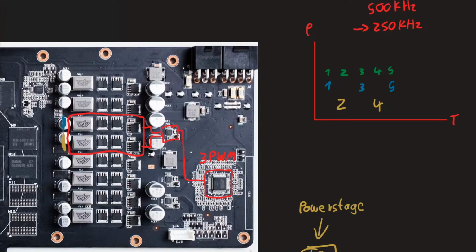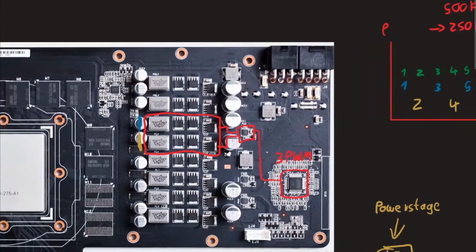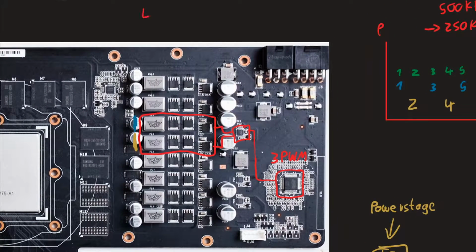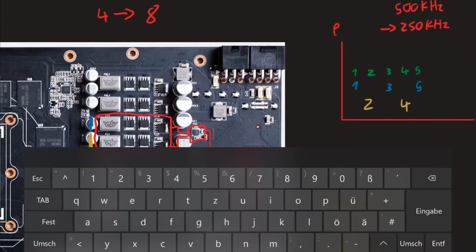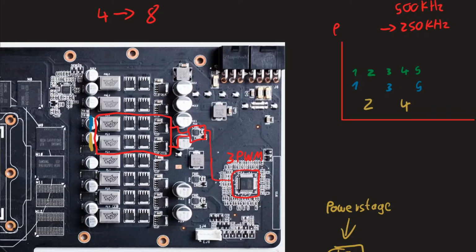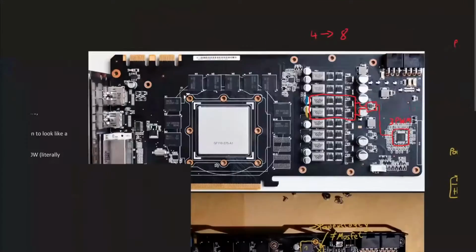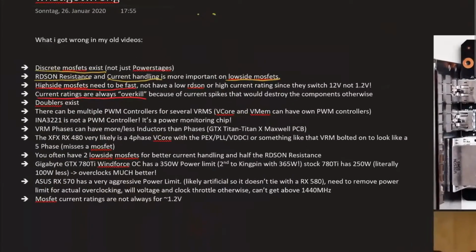An example would be the motherboard in my main PC, the Z370 Aorus Gaming 5 from Gigabyte. That one has a PWM controller with 4 phases, and it gets made into 8 with doublers, by pretty much this exact thing. It's pretty close to an actual 8-phase, though a real 8-phase would be slightly better. But it is very, very close. So that's what doublers are.